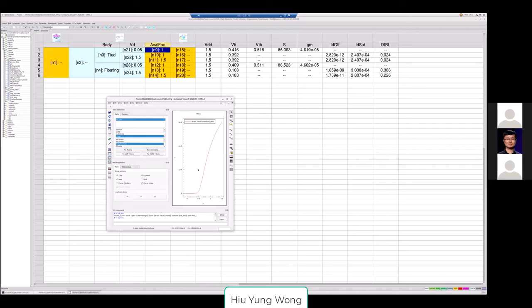Yeah, 0.5. Of course, there is more than that, because if you click log Y, on the right, all the way to the right, there is an icon, log Y. Now you make the y-axis a log scale. Now you see that it's not really 0. It's subthreshold leakage, because this is a real device. That's how you do the inspection.